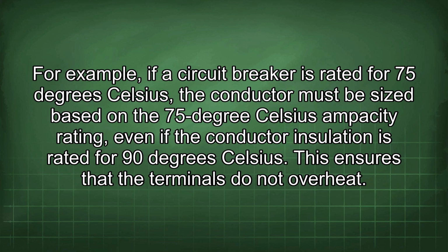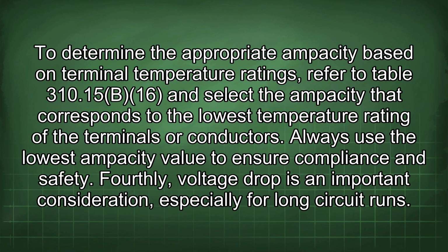This ensures that the terminals do not overheat. To determine the appropriate ampacity based on terminal temperature ratings, refer to Table 310.15(B)(16) and select the ampacity that corresponds to the lowest temperature rating of the terminals or conductors. Always use the lowest ampacity value to ensure compliance and safety.